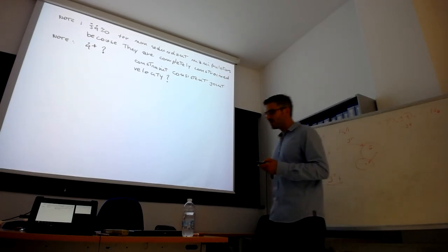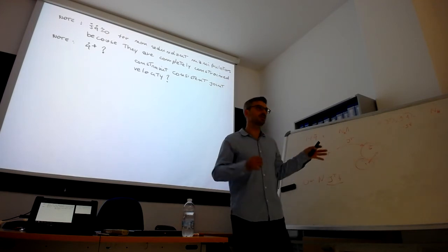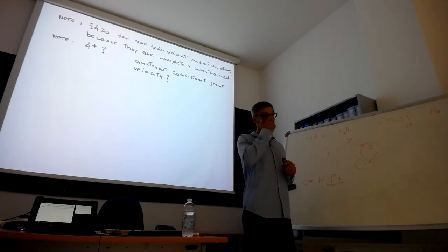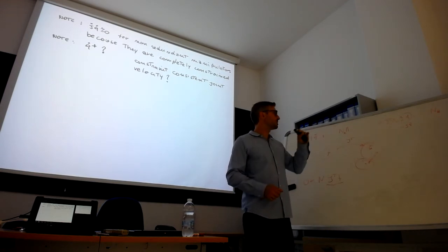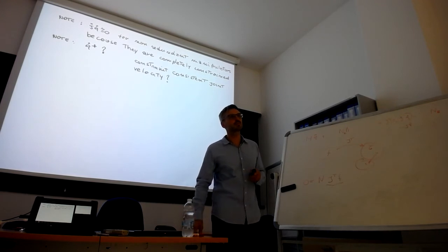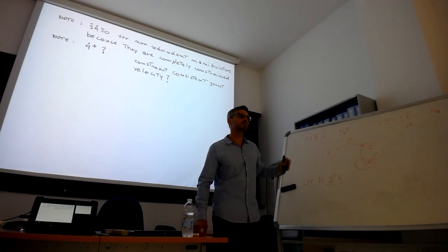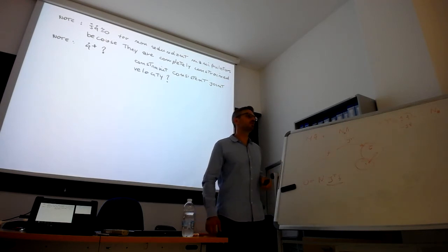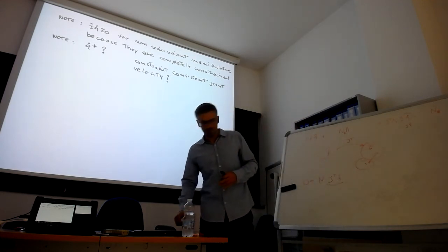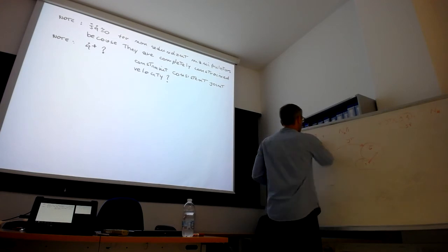But there is one problem. Whenever the robot gets in contact, what happens? The robot starts to get close to the blackboard and then touches the blackboard. What's going on? Some kind of force appears, depending on the penetration into the surface. Let's say we are using a rigid contact model, and a contact force will appear. Velocity goes to zero. So the velocity drops instantaneously to zero if we model the contact as inelastic.